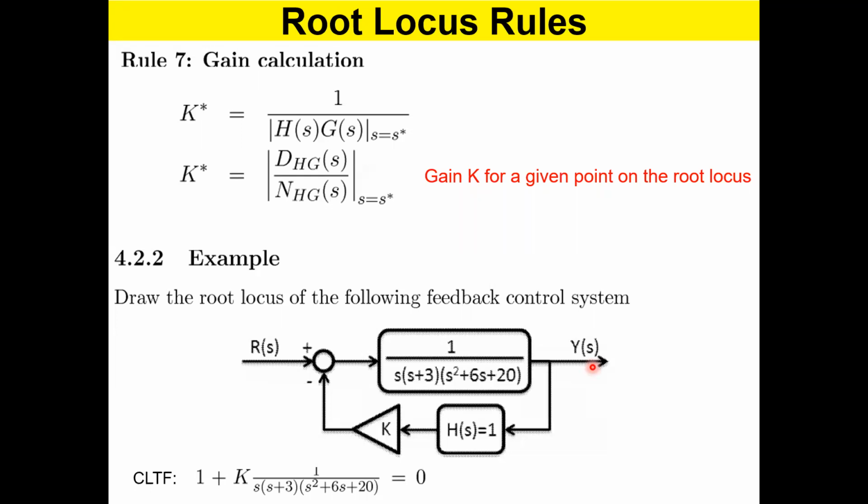So when we design feedback controls, now if you can see it over here, what we are really trying to do is to find out this value, K, feedback gain. So eventually, the whole thing of designing a control system is, for most parts, designing the feedback gain, K. Understand? For different values of K, you get different responses. And one of those responses would be exactly what you are looking for.